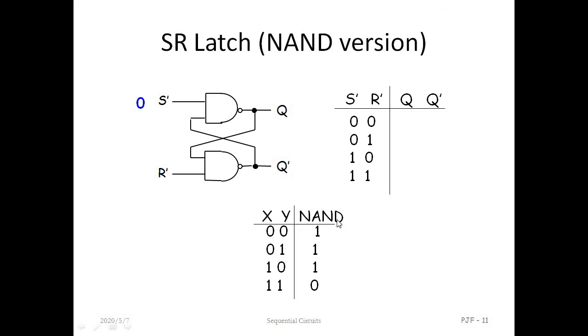XY complement. So for the first case, when you consider 0 1, one thing to add before explaining the circuit: always remember, the whole circuit is set when Q is equal to 1, and the whole circuit is reset when Q is equal to 0, and the second condition, Q and Q bar are always complement to each other. That means we always remember these 2 points.